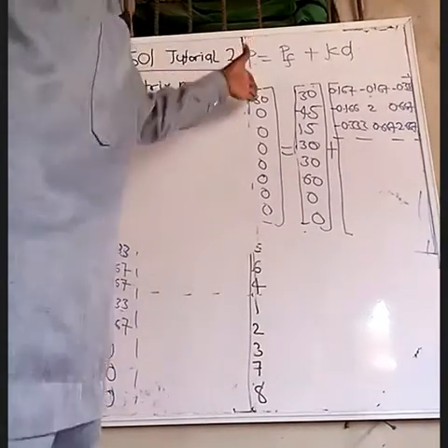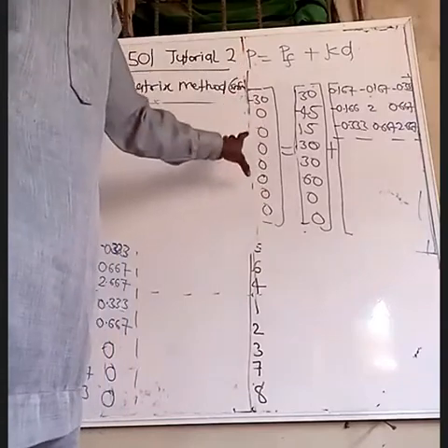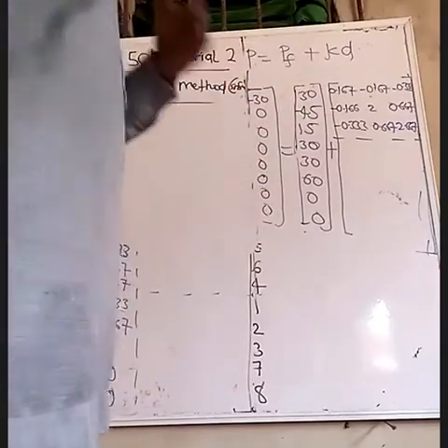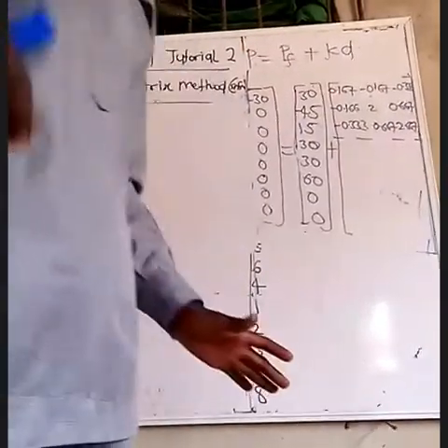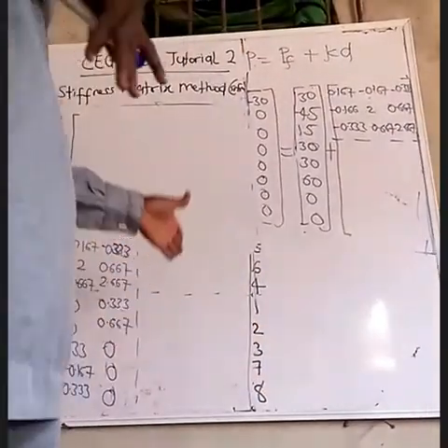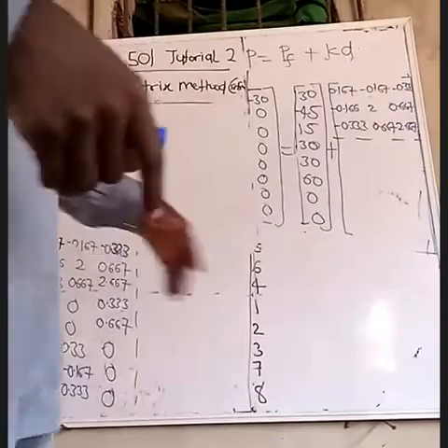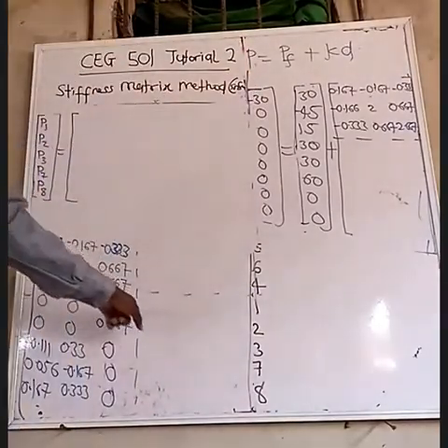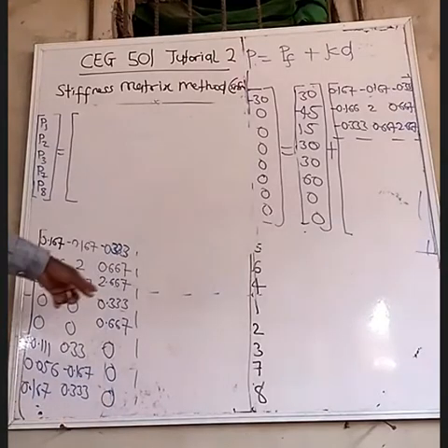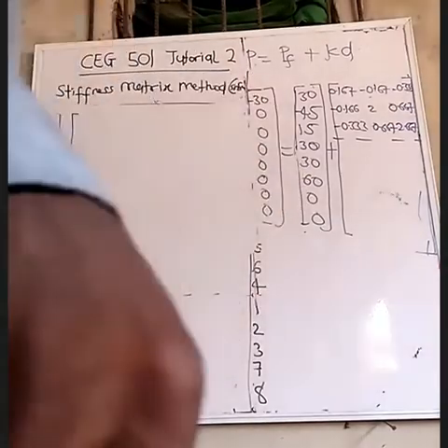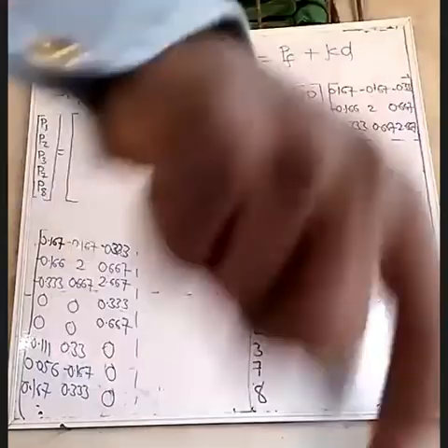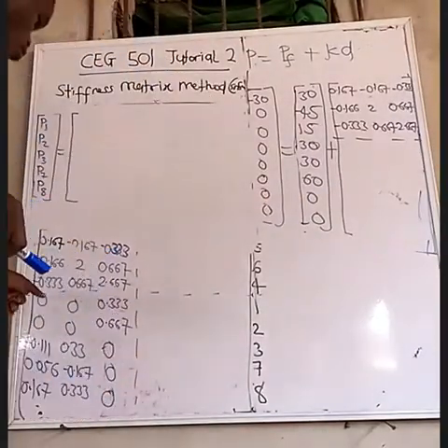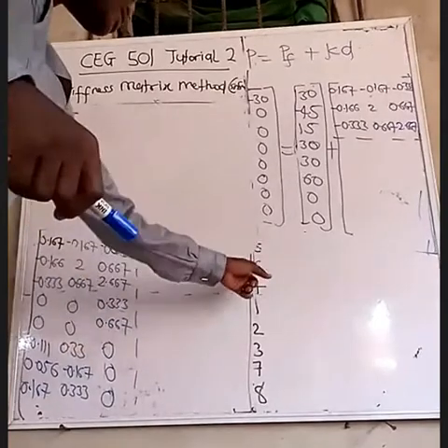This one is just load applied, as in if there was any load applied at that point, we use this formula for that. But now we want to get the actual reactions at those points. Then we need to apply this same global stiffness matrix and the values that we just calculated, D5, D6, D4. So we multiply this by D5, D6, D4.